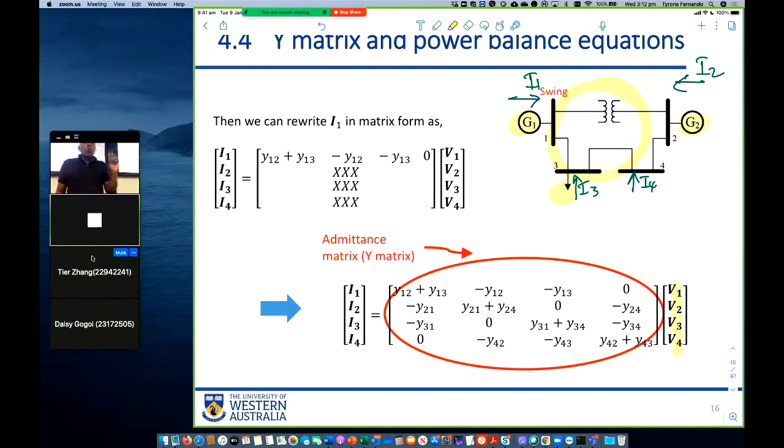So when we write the active power balance equation and the reactive power balance equation, of course there's going to be current, isn't it? Power is V I star, the complex power, P plus jQ. So there is going to be current. But if we are only going to think about P and Q and V and theta, there is no current there, so we need to eliminate current.